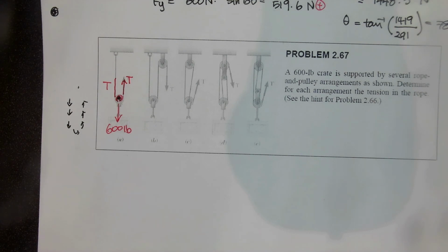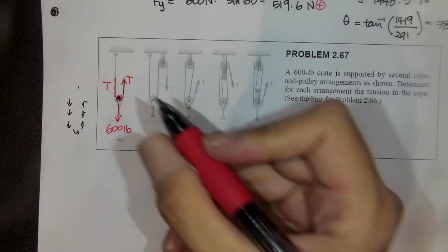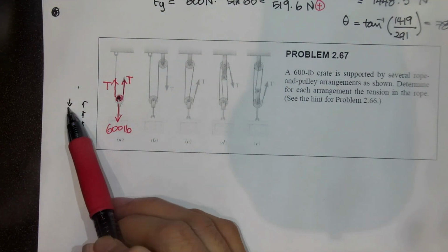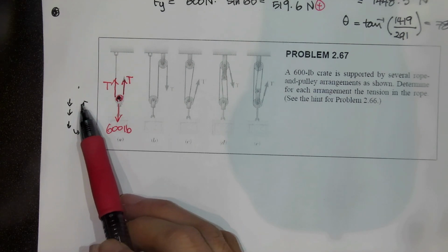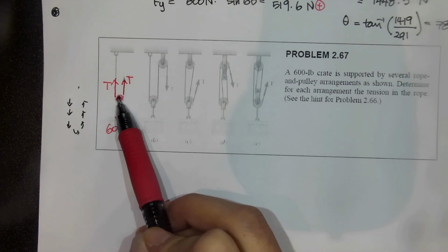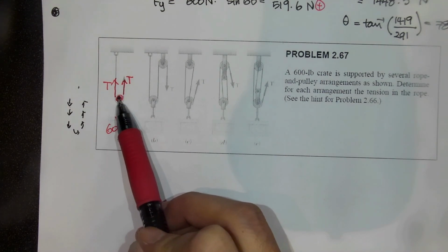If it's this side, with all other cables, then it's this side, right? It's pulling, not pushing. So that is the most important thing about cable tension. Cable tension is always away from the node, okay? So that's why it's upward. And I know your thought process is the same direction, internal force should be this direction, but we are thinking about this point, and cable tension is always away.